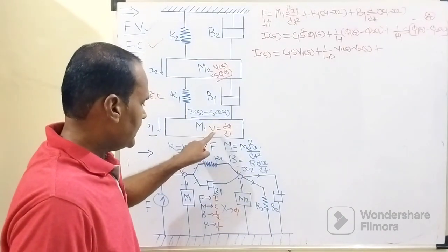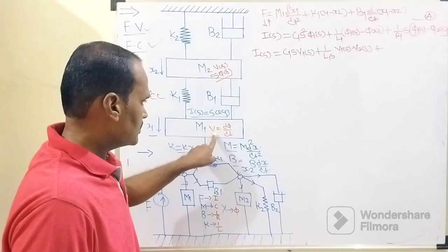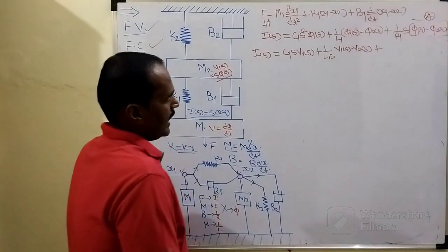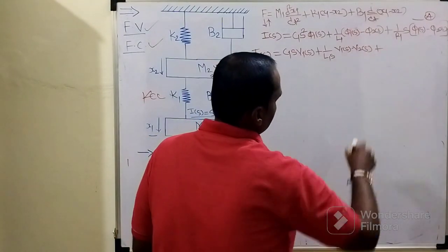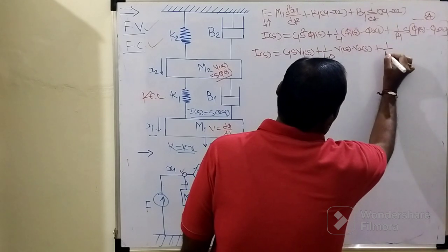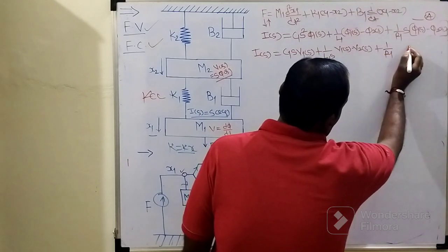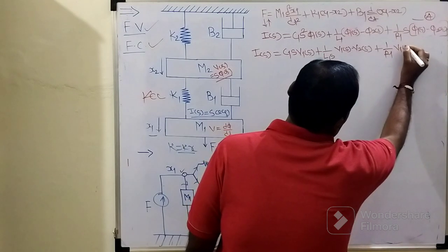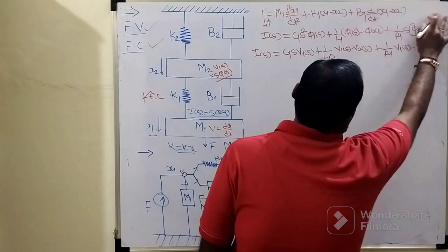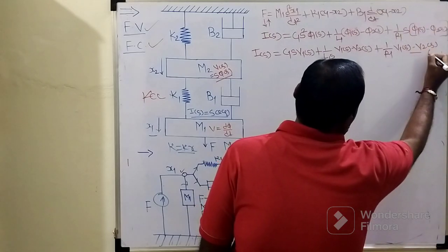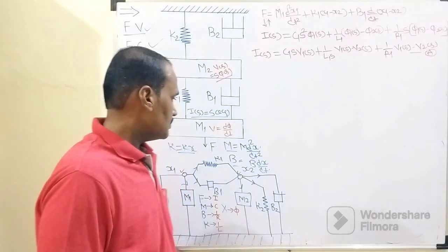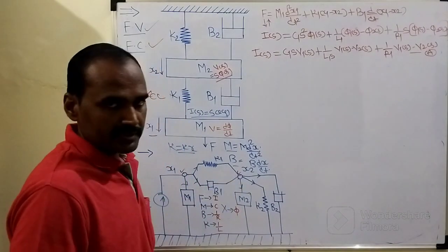And when we apply Laplace transform to this substitution, it will become V of s equals s into phi of s. So phi 1 of s minus phi 2 of s, obviously it will become v1 minus v2, then the remaining is 1 over r1 into s into phi, which is nothing but V, so it will become v1 of s minus v2 of s, right? Now this is equation number capital A, right? So in this same manner, we need to obtain the system equation at node number 2.